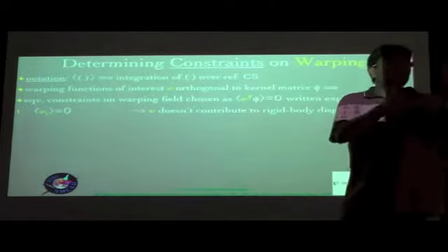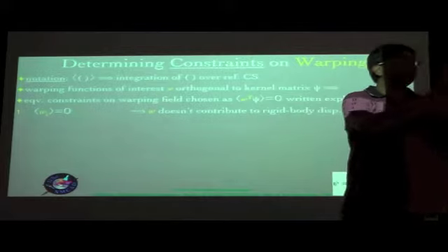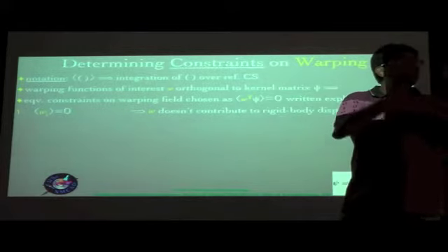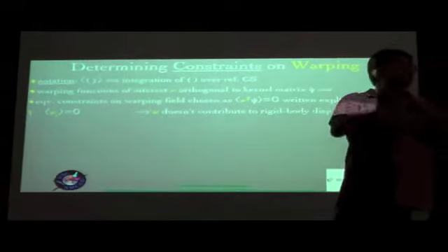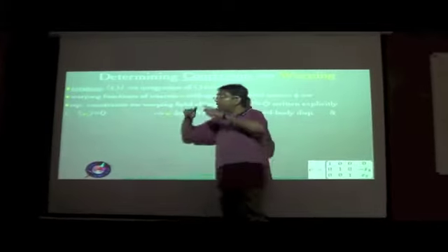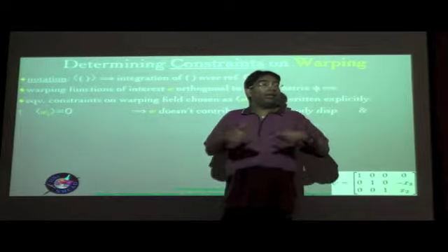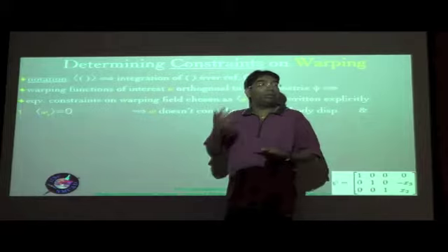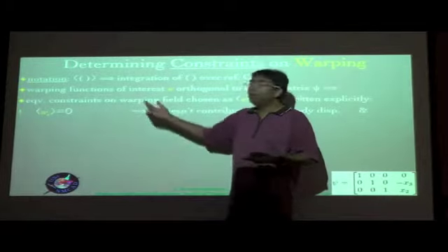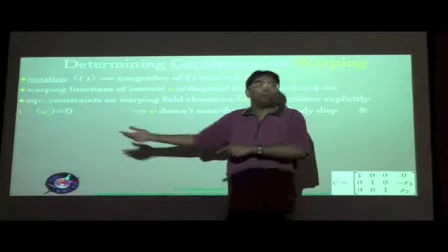The average W2 basically means motion like this, which is again a rigid body like translation, and an average W3 basically means a translation in the vertical direction or in the x3 direction. So all that we are saying is that when we average it out, or integration divided by the area, is nothing but the average. Because area is a finite number, an integration over the area also means the same thing as talking about its average as well.